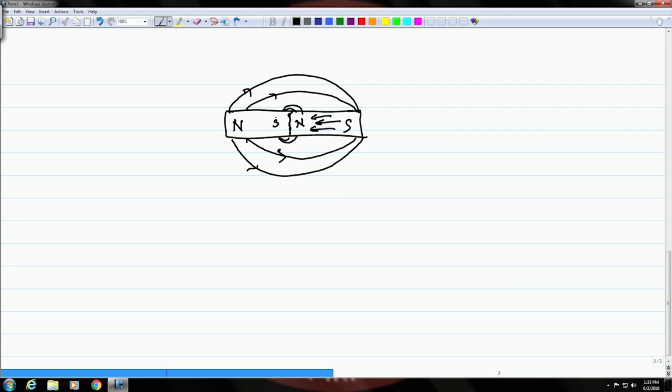So, if the magnetic domains in the parent material are like this, around this discontinuity, they will be perturbed by the magnetic field of this tiny magnet which is created due to the presence of the discontinuity. So, this is the phenomena of magnetic flux leakage, as I said.